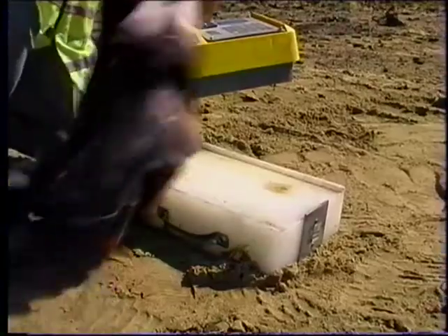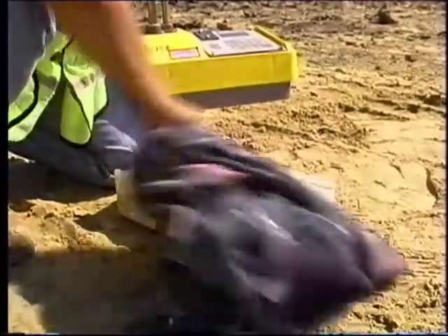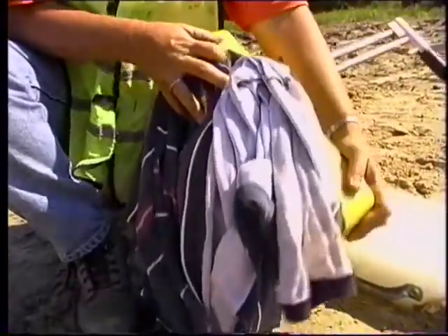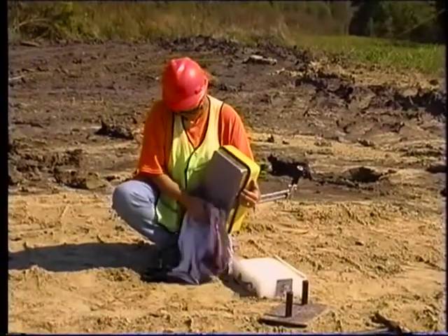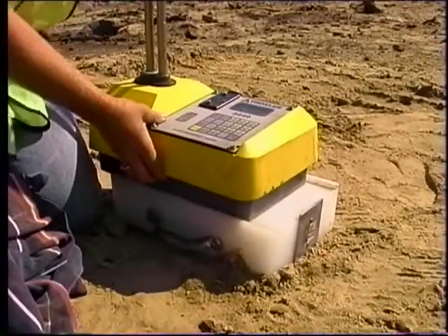Clean the top of the reference standard block. Keeping the source rod retracted inside the machine, clean the base of the device. You want to make sure there is no soil or other material to prevent a good seat between the device and the block. Air gaps between the device and the block will make the test results invalid.